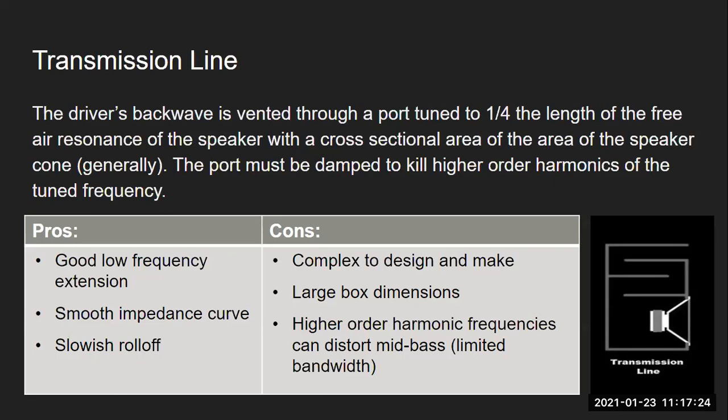You mechanically delay the sound wave coming off of the back of the driver by a quarter of that wavelength, and then you pipe that out to the front of the speaker, or around the front of the speaker. What that does is it creates constructive interference. And typically, because there would be destructive interference in higher frequencies, you'd want to put in a lot of damping along the way to help take out those higher frequencies, so they don't make your frequency response suffer in the mid range.